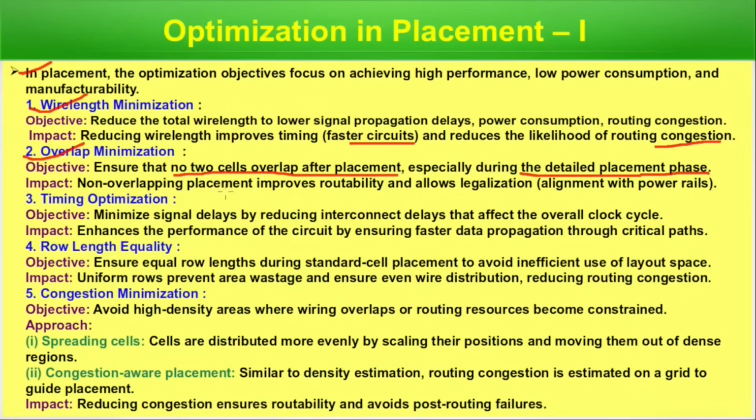Impact: no overlapping placement improves routability and allows legalization alignment with power rail. Timing optimization objective: minimize signal delays by reducing interconnect delays that affect the overall clock cycle. Timing optimization is also done. Impact: enhances the performance of the circuit by ensuring faster data propagation through critical paths.